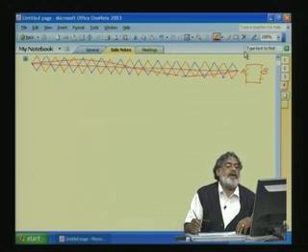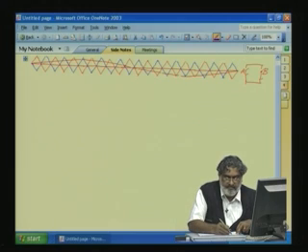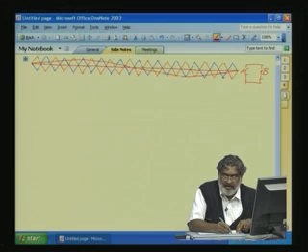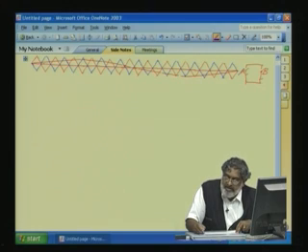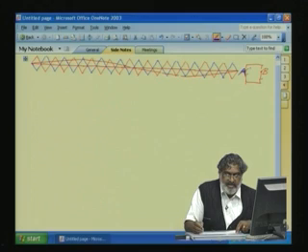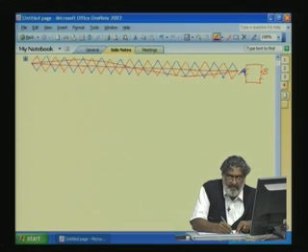Now, let us draw the switching pattern. First one, let us take for leg A. Leg A, which triangle will we be using? The blue triangle we will be using for leg A. So, I will mark it accordingly. A is here. So, whenever sine is greater than the triangle, top switch is on. So, here for leg A.